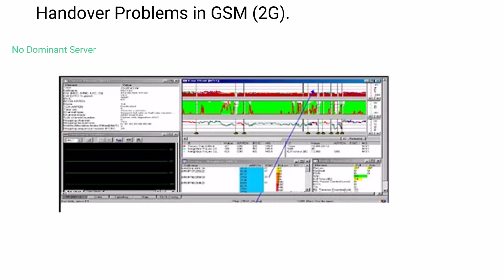Impact on network and user experience. Frequent ping-pong handovers can occur because the phone sees multiple equally strong cells and continuously switches between them. Increased signaling load on the network can reduce overall efficiency, potentially leading to degraded call quality or dropped calls if handovers are not well tuned. Reduced data throughput due to increased overhead and shifting among cells. Mitigation strategies, coverage, and capacity planning.